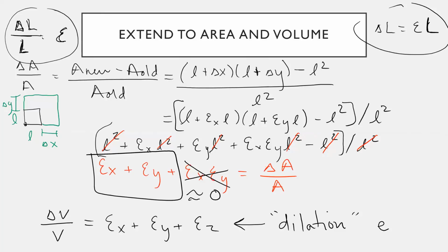And just one question. Yes. When you were multiplying by strain Y and delta x, why were you multiplying by L squared? Or did you just, I did the FOIL. And the L originally, so strain X L, that's delta X? Yes. Because this equation here can be rewritten to say that strain times your initial length is your change in length.